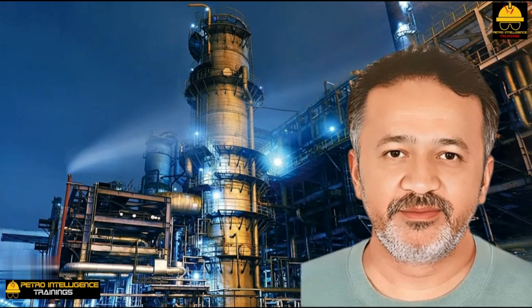Vapor binding. We can measure the non-condensable concentration in the flow of a mostly condensable vapor such as steam. However, the actual concentration of non-condensibles in contact with the condensate layer around the tube wall or inside the tube is much greater. While the condensable vapor condenses and drains away as a liquid phase, the only way the non-condensibles can escape from the tube surface is by diffusion backwards against the bulk of the vapor flow.